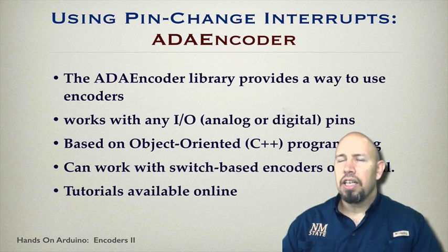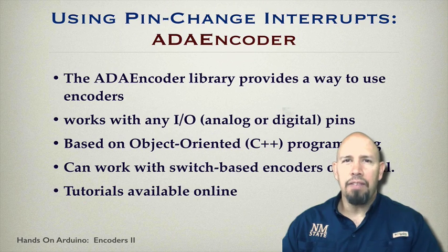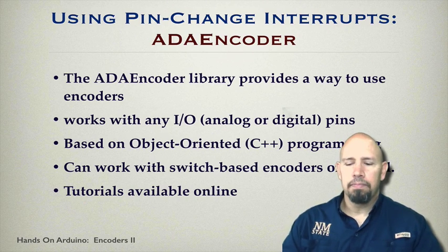In this case, the library is not as simple and straightforward as a lot of other libraries. It's got some subtle things that make it kind of complex. So, in the vein of having you understand what's going on, I'm going to lead you through how to work with pin change interrupts in order to do this decoding.